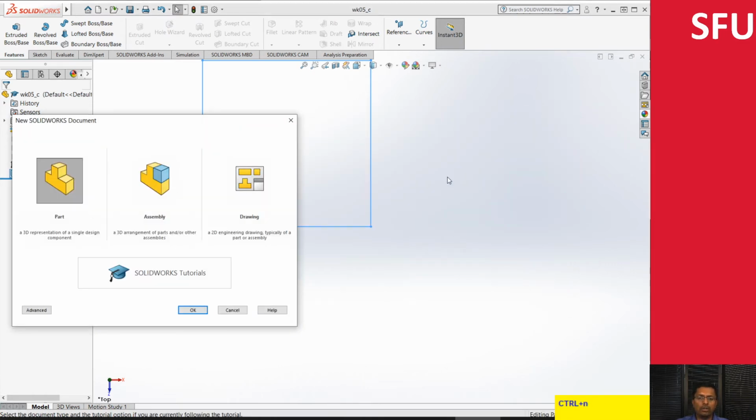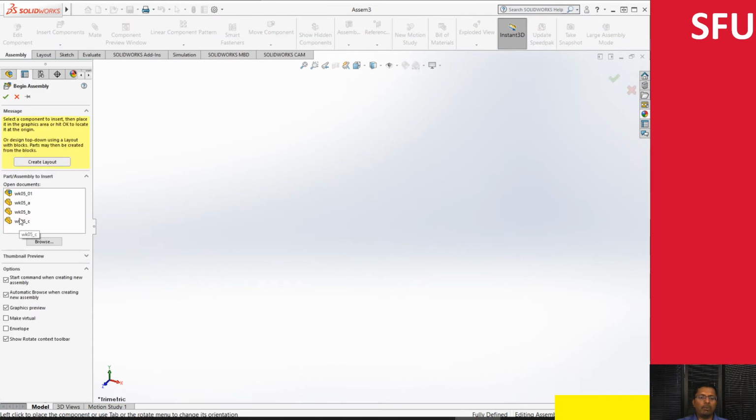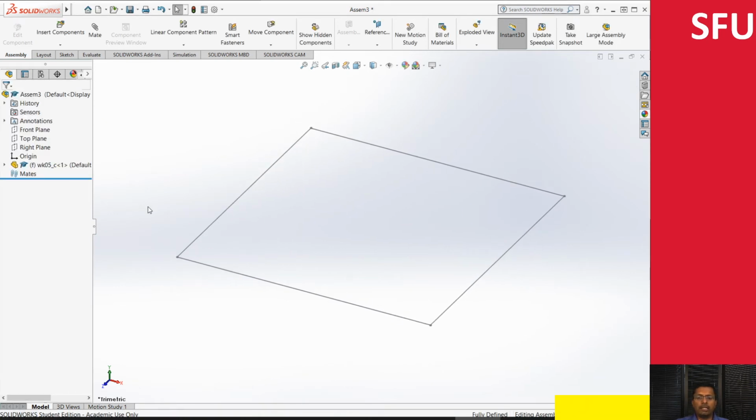I know I haven't actually extruded the table as yet, but nonetheless, let's see what happens if we try to import the part as is inside our assembly. So I'm going to click on new assembly, and I'm going to click on part C and insert it over here. Obviously this just looks like a sketch. The reason being I didn't actually extrude the part out.